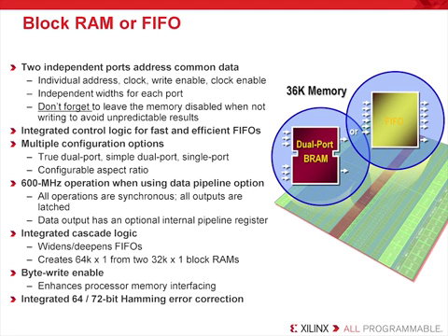The block RAMs include a configurable aspect ratio functionality which allows each block RAM port to have a customizable width. This helps the memory lend itself to more applications and ensures efficient use of the block RAM. For example, this means you can write to port A in bytes, plus use the parity bit, then read from port A serially with no access to the parity bit, and then also write to port B in 16-bit words, plus using 2 parity bits, and then read from port B in 32-bit words plus 4 parity bits. So there's really quite a bit of flexibility as to how you use your addressing of this memory when targeting the block RAM.